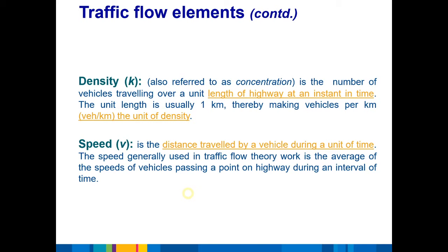That causes a great deal of grief. There's a lot of roads in the States. I'm not familiar with the particular ones you just mentioned, Hayden, but I know there's a lot of roads where the average speed of drivers is about 80, despite being signed at 100, and a lot of those roads are being flagged for potential speed reductions to 80. But then you do get 20-30% of drivers who get very upset with that because, exactly as you say, the speed limit does not feel like it matches the road. One of the biggest dangers, and what's trying to be corrected there, is that differential speed between some people traveling at 80 and some people traveling at 100.